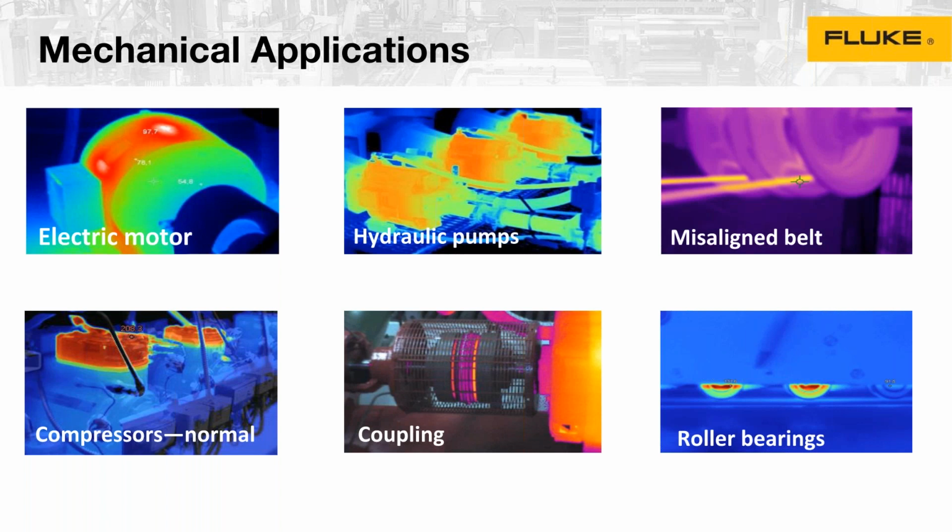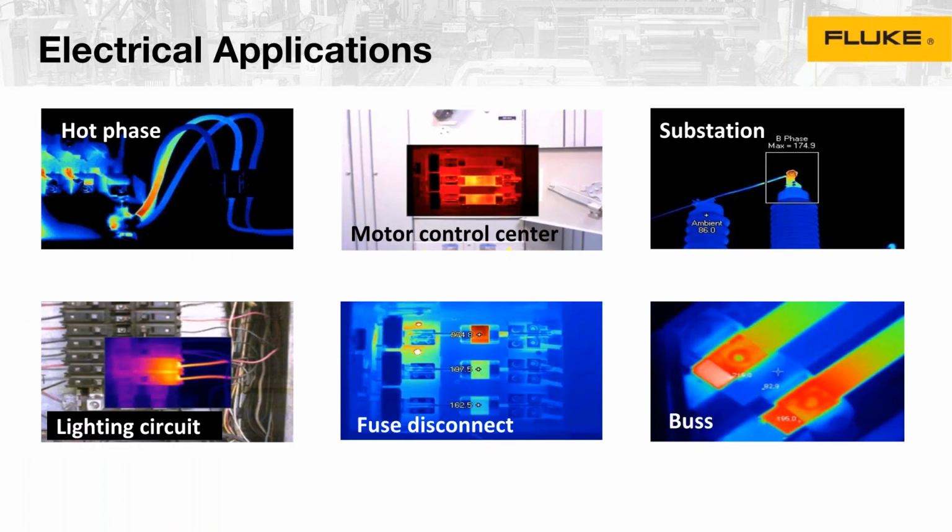It may not just be the motor, but it may be just the bearing. But if the bearing goes bad, you have to have the ability to actually see this. And there's very little parameters that you can measure on a bearing, maybe from a temperature standpoint. And so visually looking at the temperature and an increased temperature on your bearings has a big impact.